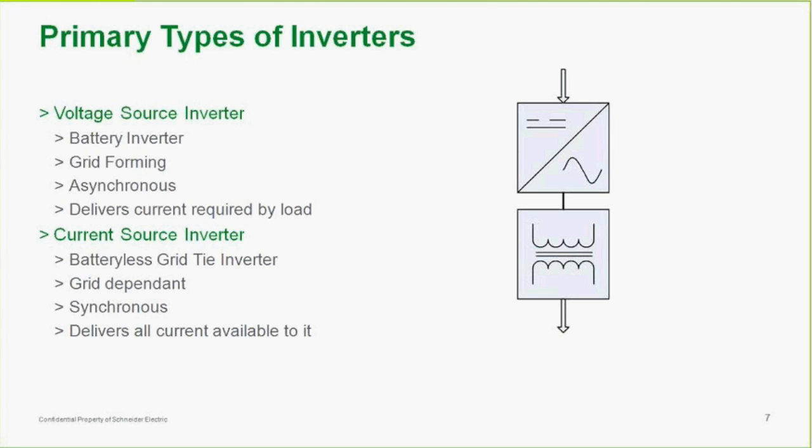Now I'll do a transfer switch, tie a very small generator to the output of my batteryless grid tie inverter, and fool the inverter into thinking there is a grid. Yes, it can work. If the generator is of sufficient quality output, it can trick the batteryless inverter.